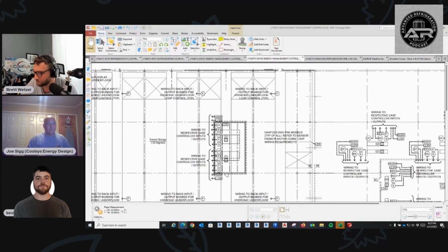But I mean, we've got all these jurisdictions that don't know what CO2 is, and their inspectors are all very, let's say, hesitant about these new system installs. So we have to show leak detection in our documentation, whether it works or it doesn't, because it makes them more comfortable and able to sleep at night, right?